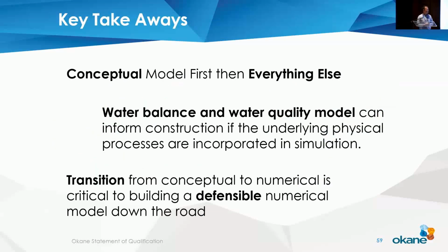So key takeaways, again, I like to emphasize conceptual model first, then everything else. And water balance and water quality can indeed inform construction, as shown in case study number 2. But we also need to make sure that water balance is done first, then water quality. Water quality is a lagging indicator. When you see something bad in the water quality, you are too late. So you really want to focus on one of the leading indicators, that is water balance, among others, before you look into water quality.